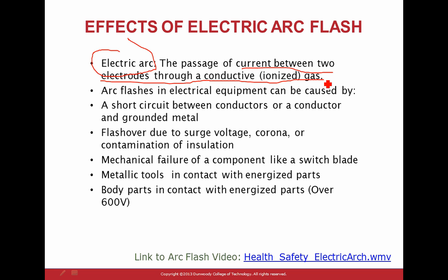A short circuit is when you grab a hot and a neutral, put them together, and preferably you bolt them. If you have bolted them, that's a short circuit. An arc flash is when you accidentally drop, say, a screwdriver that's not insulated, and it leans on phase A and the enclosure, creating what they call high impedance. That high impedance, believe it or not, is destructive. It creates a big ball of fire.